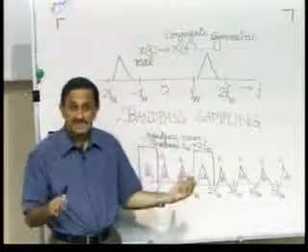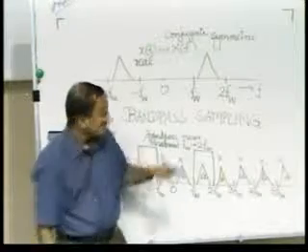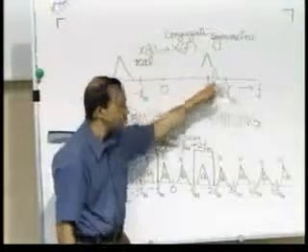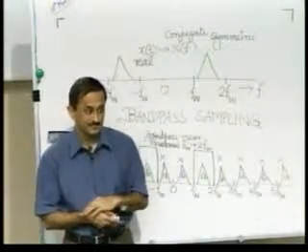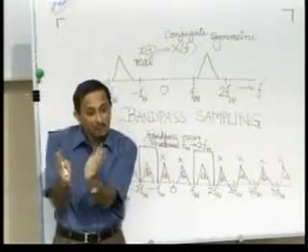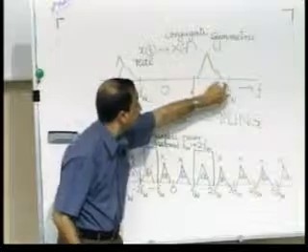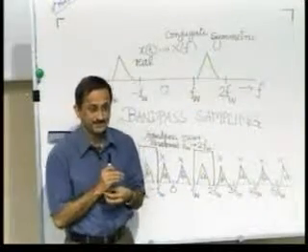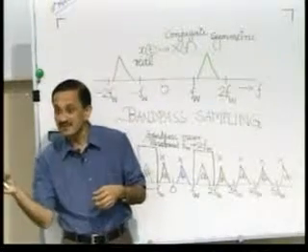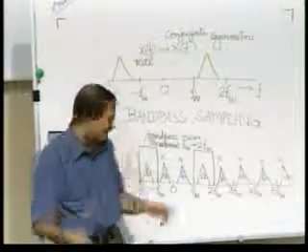So, what this problem of inaccuracy of sampling rate indicates is that normally it would be desirable to choose an FW in such a way that you have a gap on both sides. So that you fit your spectrum not exactly between FW and 2FW, but well in between or within. So actually it is this gap that allows you some tolerance. So that gap is left there intentionally. You have chosen FW and 2FW in such a way that you have a gap. And then if you sample at 2FW plus or minus a little delta, you still have some tolerance.